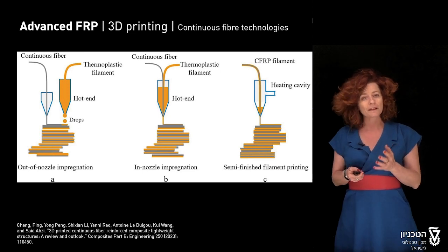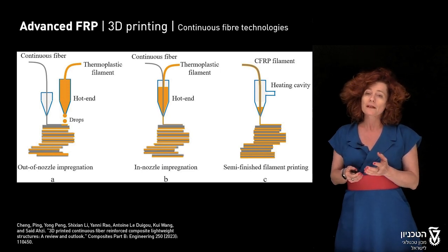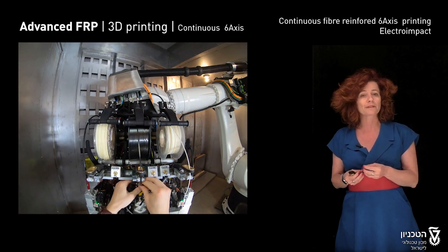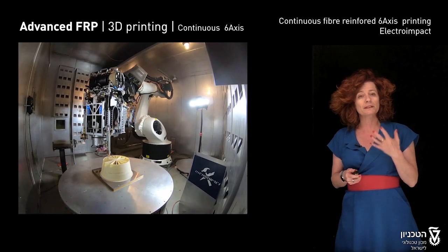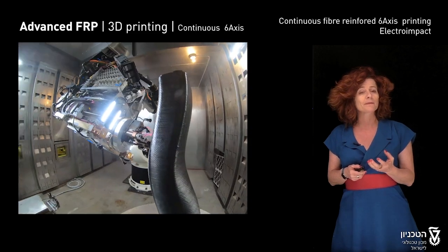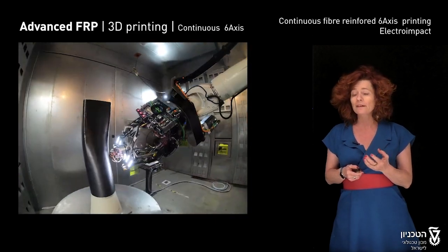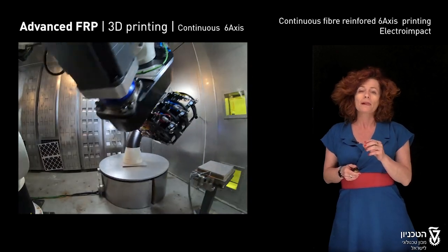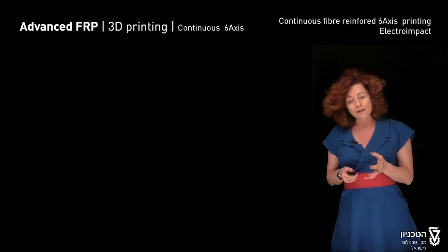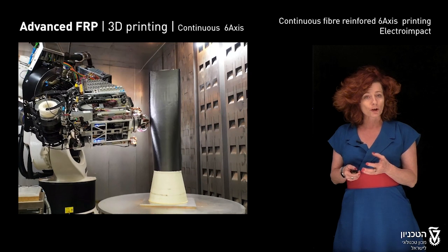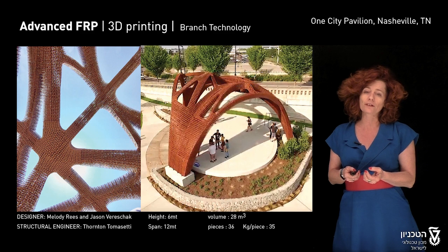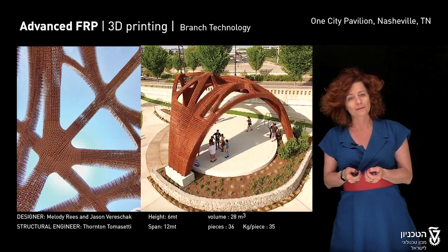Now this is a problem not yet fully resolved in composite materials, since the full capacity of these materials is with a continuous fiber. That is the part that takes the load. That is where the material is in full performance. This is complicated, and that is, say, almost impossible in 3D printing technology as of today. There are some developments interesting to follow of continuous fiber and material deposition. Some other examples exist where fibers are chopped in the mixture, and this is one fine example of the use of this technology on an extremely large scale.